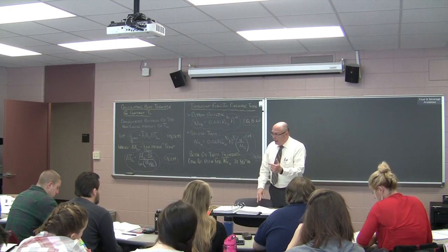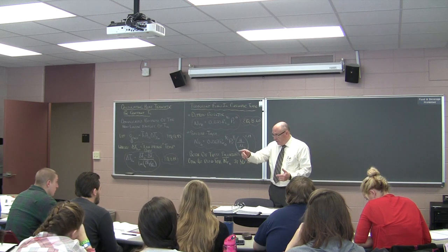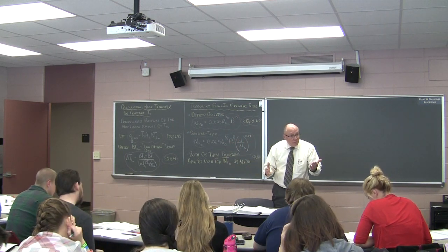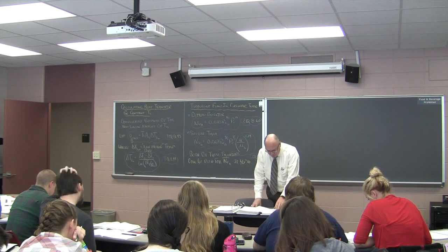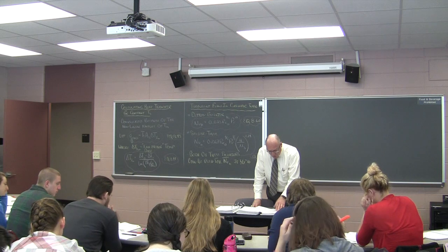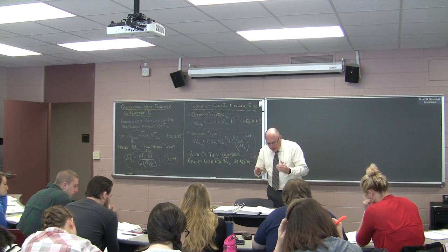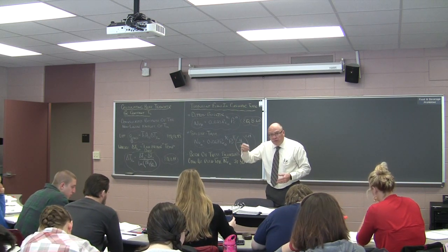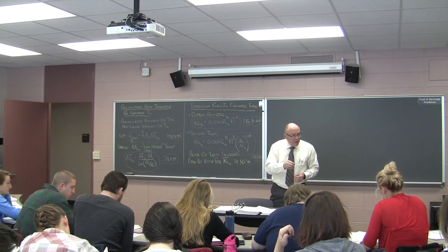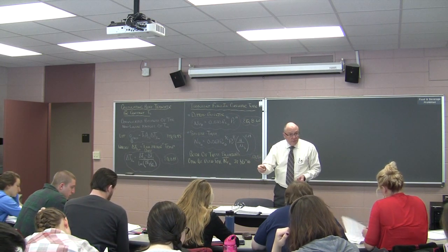All right. Now, I think it was Darren that asked the question, are these for constant surface temperature or are these for constant surface heat flux? I want to direct your attention to page 517 underneath the Sieder-Tate equation. Oh, and before I get there, in the Sieder-Tate equation, the viscosity in the denominator is evaluated at the temperature of the surface.